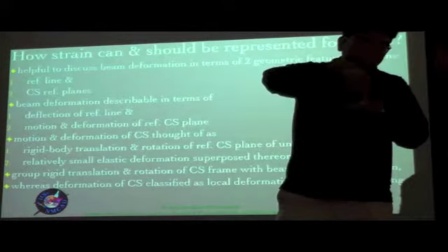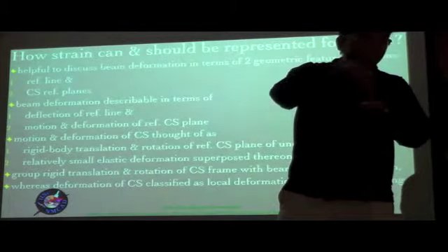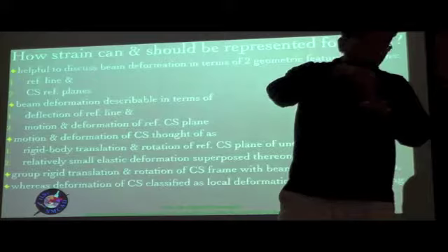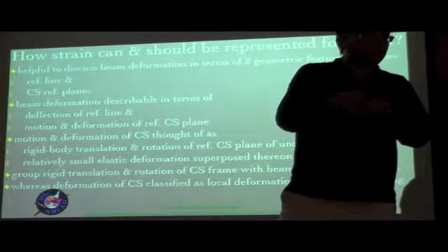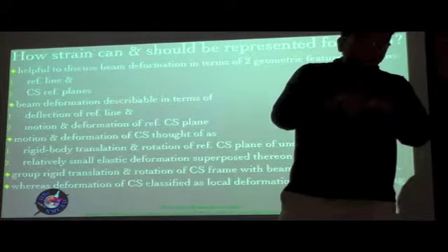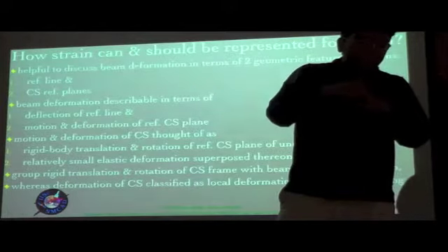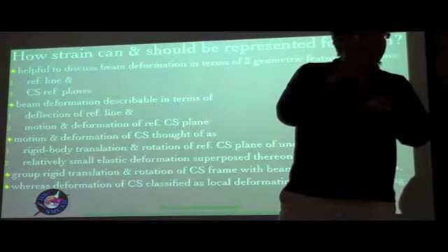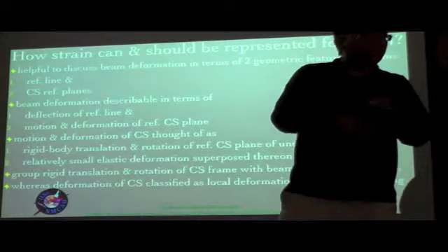Now if you're talking about a line element over here, I can average out the displacements due to warping basically on that line element, which means I can integrate with respect to x3, which is the thickness coordinate, from minus h by 2 to plus h by 2, if h is the thickness of this strip, and then divide by h. So I get the average, right? Similarly, I can take its derivative with respect to, let's say, x2, and then I can take its average similarly, that is, integrate from minus h by 2 to plus h by 2 and divide by h.